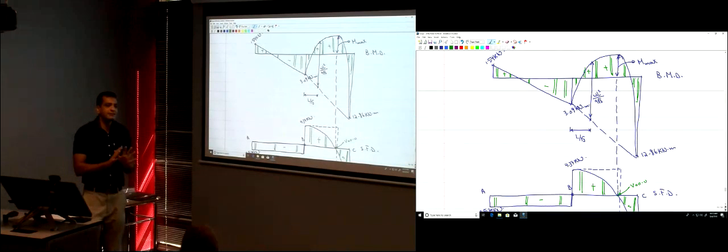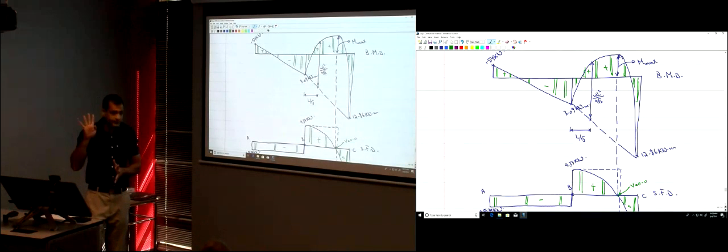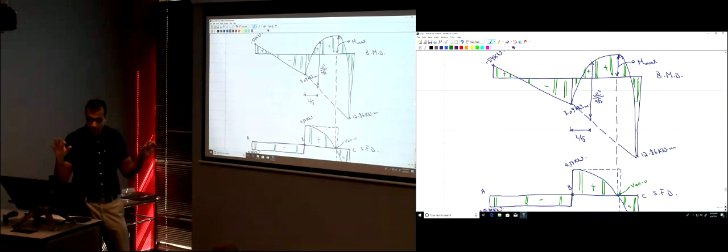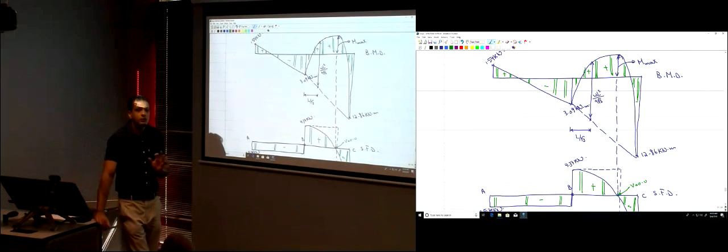So those are the steps of the slope deflection equation. We use those 4 steps. Again, they are so simple. First, break down your structure into the individual members. Find the kinematic degrees of freedom. The second step, write the slope deflection equations at the 2 ends of each member. To do this, you need first to find the fixed end moments. Those can be found from the back of your book.